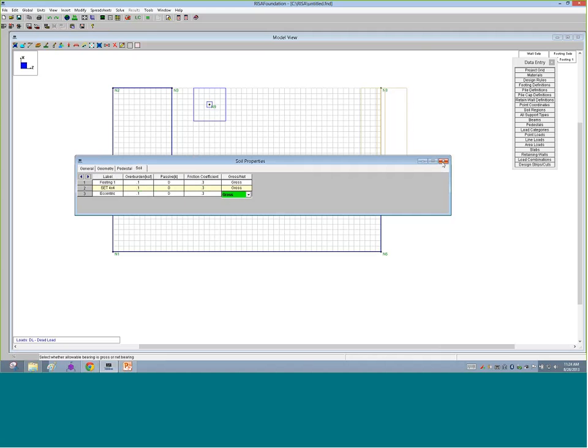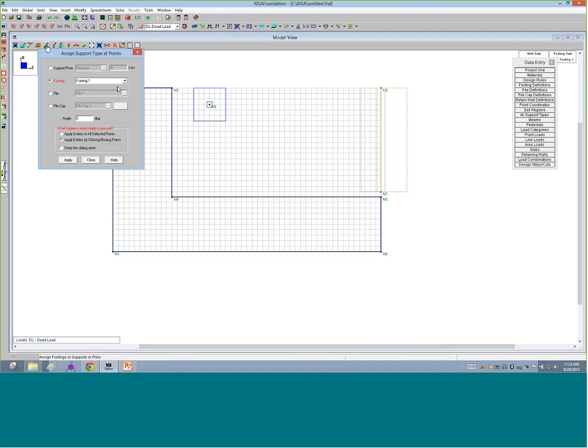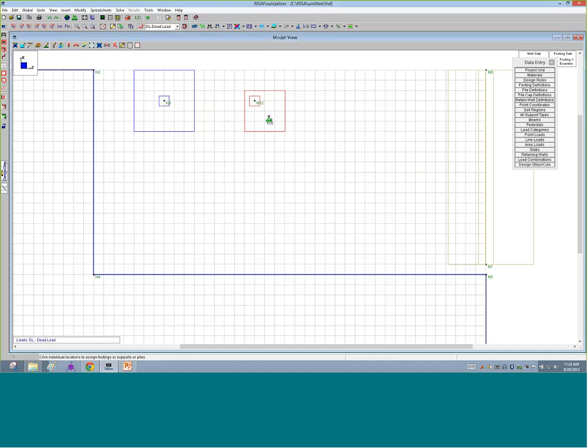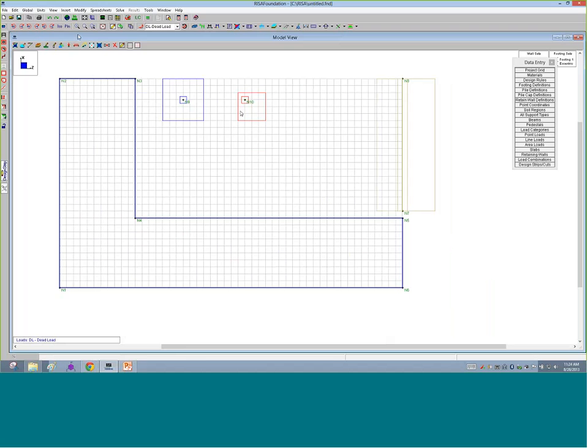So I'm going to go ahead and close that down. I'm going to draw a footing in, using that eccentric one I defined. So I'm going to tell the program here, use the eccentric, and you can see it's offsetting that by 12 inches in both directions from the center line. So if we look over by 12 inches this direction and 12 inches this direction, and up by that direction there, it will size around that offset.